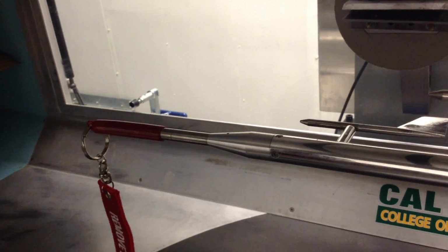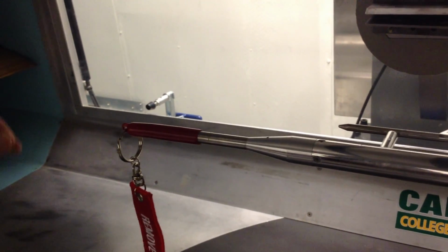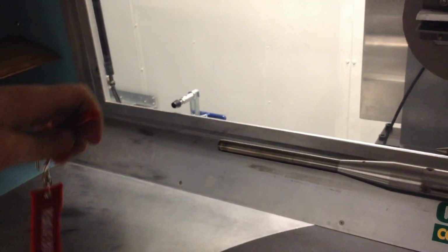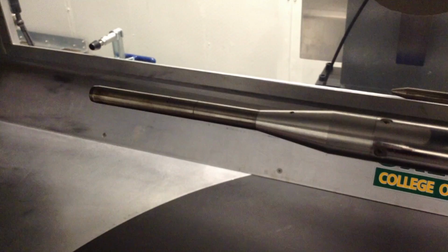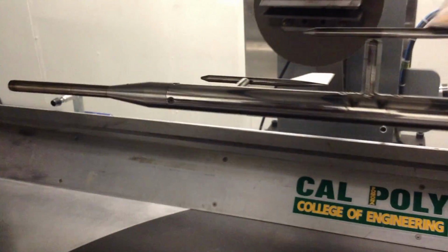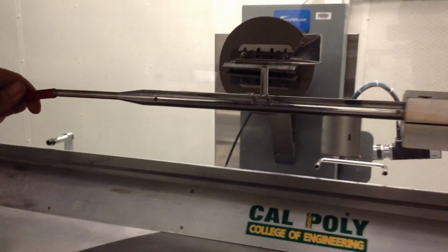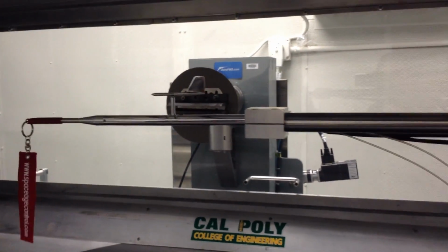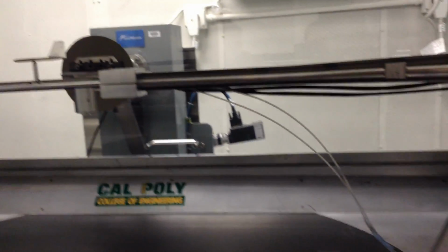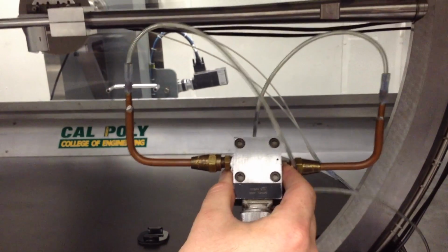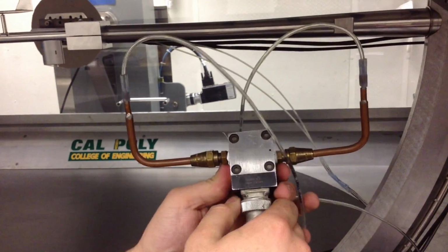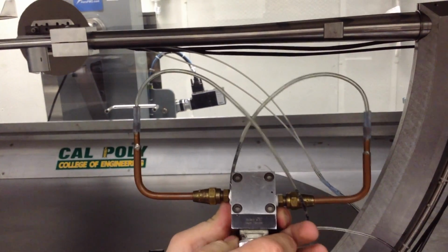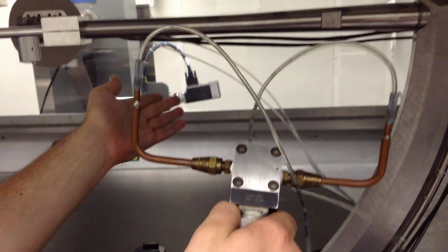Also contained in the alpha beta probe are pressure ports. In the nose of the probe is a dynamic port, and at the top is a static port. The static and dynamic ports are used to measure the pressure inside of the wind tunnel. The pressure transducer, which is located right here only for demonstration, during normal operational activity is located underneath the wind tunnel and on the back side.